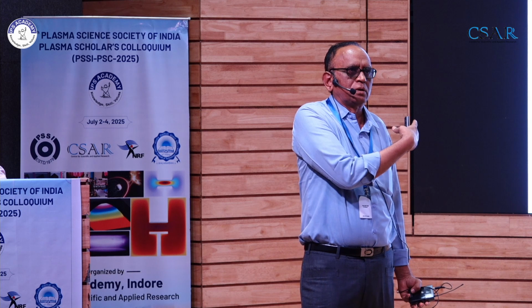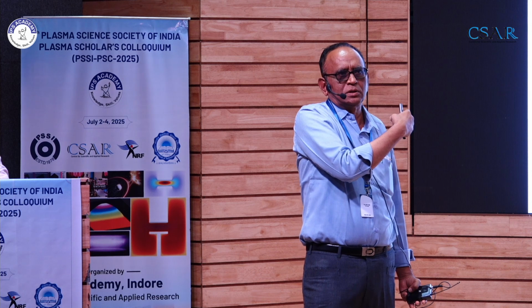Soot formation is bound to be there because, see, when you do this deposition, you have to make sure that a certain set of radicals are surrounding your substrate. And soot formation will be on the chamber walls. It cannot be on the substrate because of your abundance of atomic hydrogen. And that atomic hydrogen etches the sp2 bonded carbon chemically.